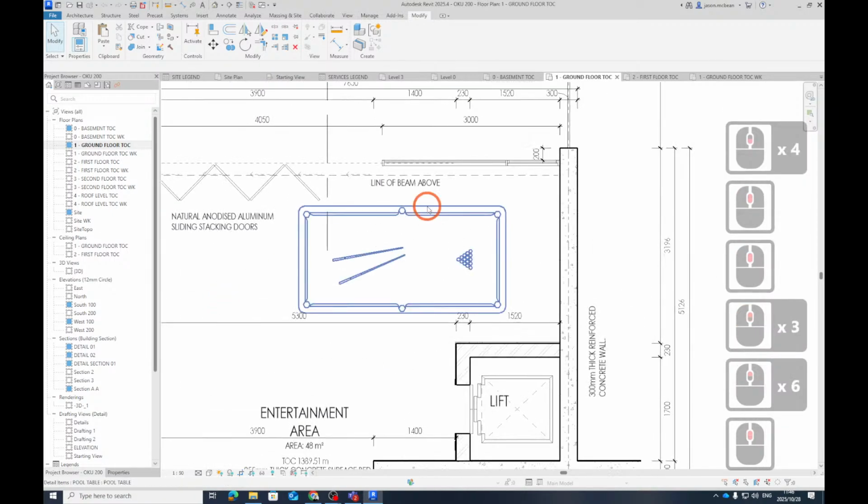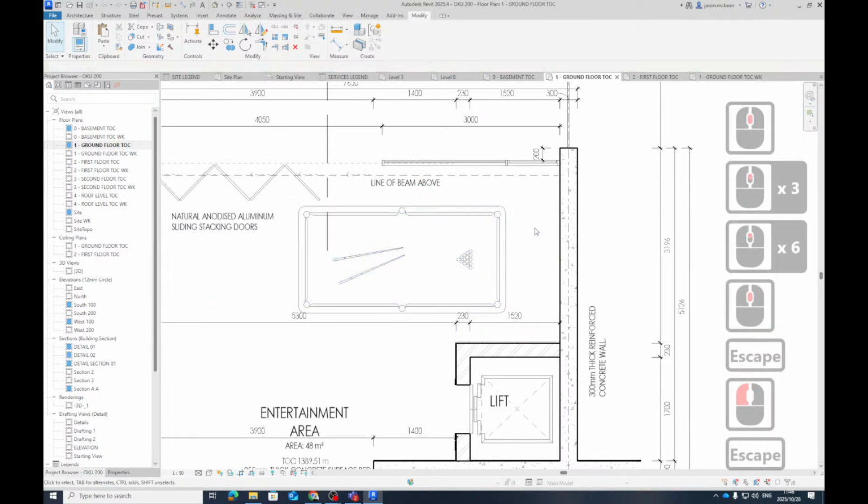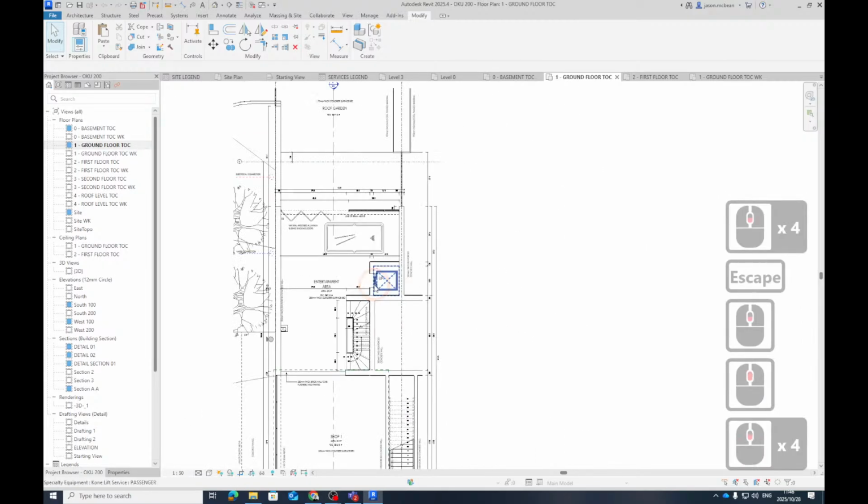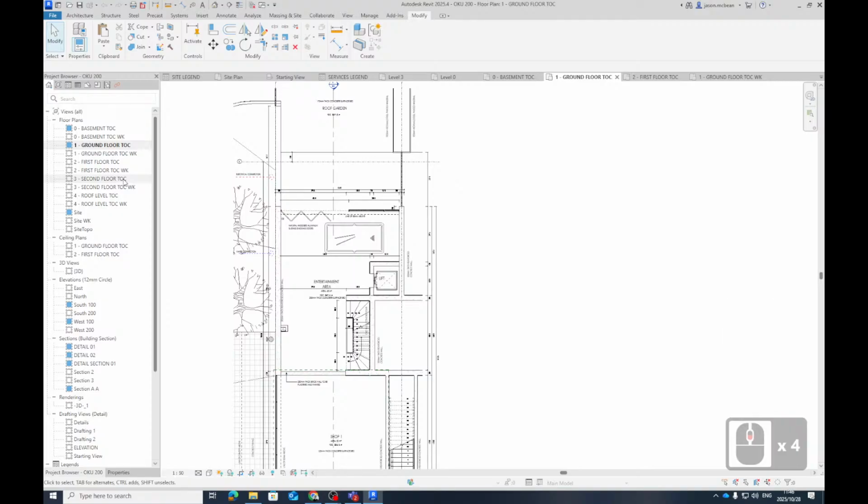I sometimes show a bit of furniture, but it's always grayed out, and it's just there to inform. But everything else is drafted. And the kitchen is important, right? The kitchen counter, not all the little chairs and stuff around. Just the stuff that's getting built in by the contractor. Mine's got those industrial kitchen tables and stuff. Do I just leave them excluded, blank? Yes, and then if something's built in, then show it. So that kitchen counter is very important, that's built in as part of the design. And if there are built-in display cabinets and stuff, include them.